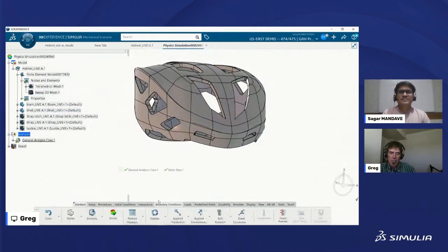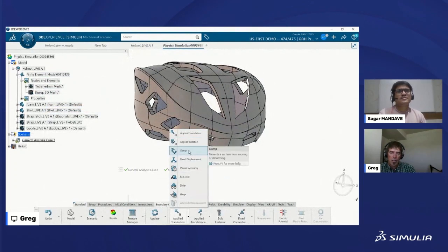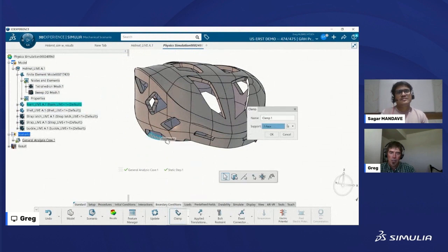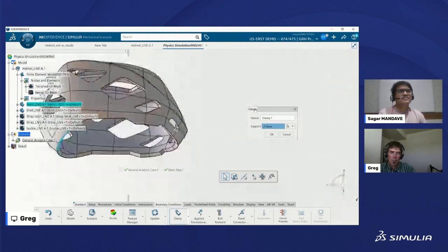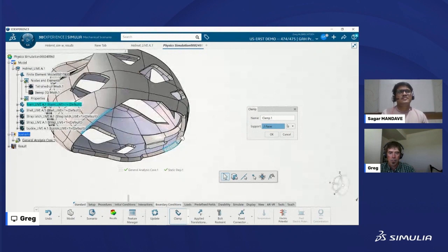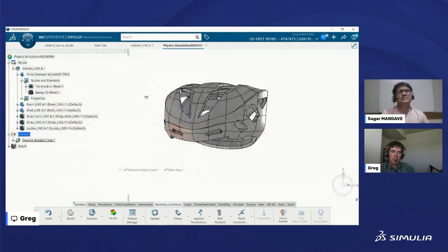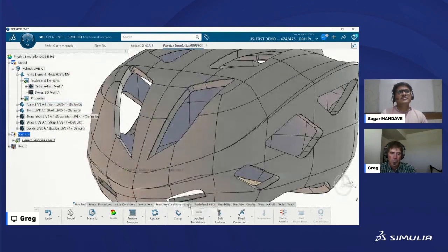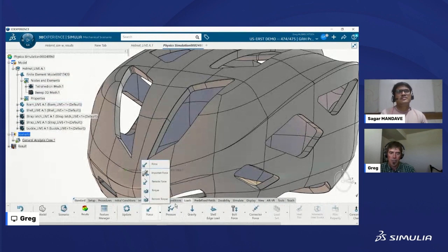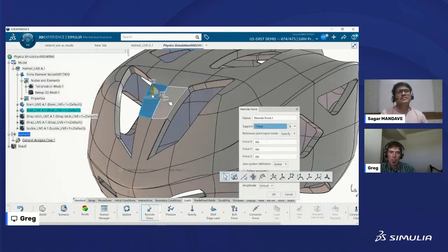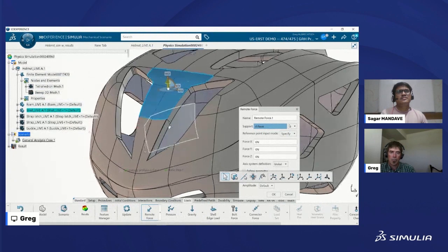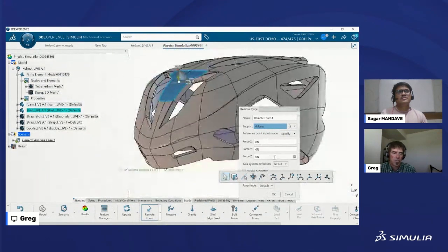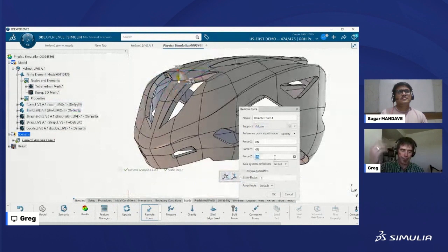All right, let's add some boundary conditions. I'll just go ahead. I'll clamp maybe here, spin this around, clamping, doing pretty good. And let's go ahead and put a load. Select loads, lots of different types of loads. I'll say remote force. Let's just go ahead and pick those for the force location. You know, maybe we'll simulate an impact to a tree or something like that.